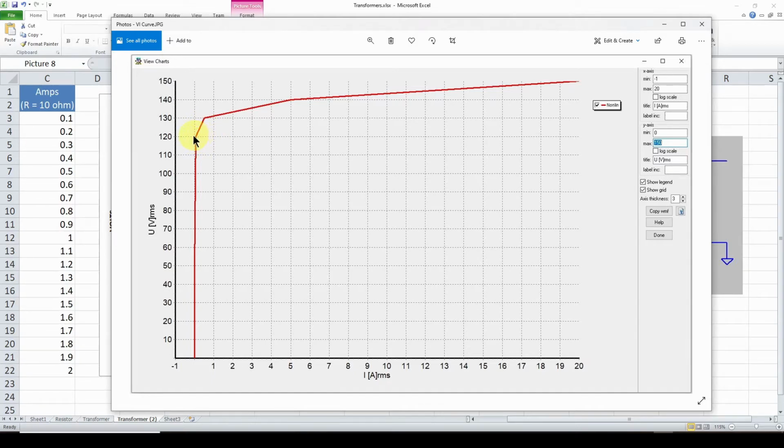Well, I know that it's rated at 120 volts. Now, engineering-wise, you generally consider plus or minus 10% to be a typical range of accuracy. So 10% above 120 is about 130. My guess is that we can expect to be fairly linear up to maybe 10% over normal voltage. So that's maybe 130.